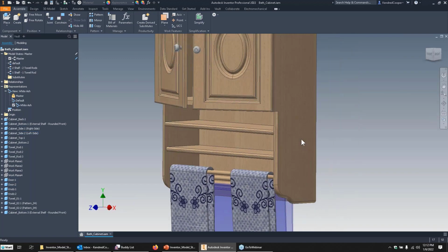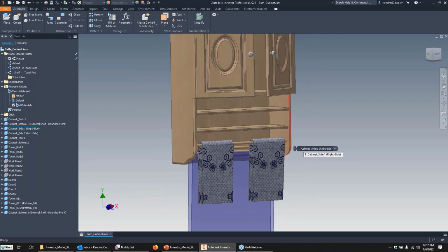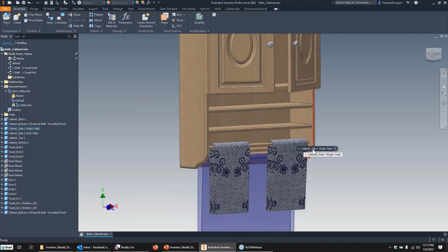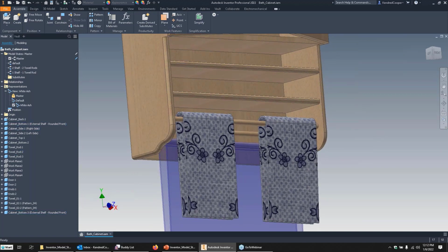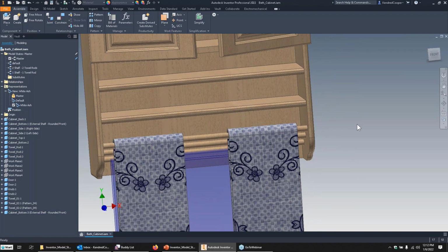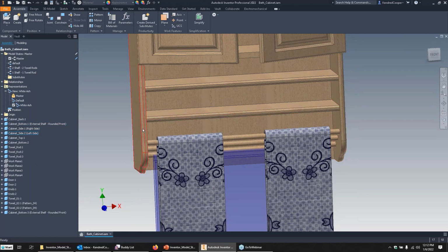Same thing for the side panels. That's really the big heavy hitter in this. I've got 3 different configurations. Well, 2, but I could have more. I've got 2 configurations already set up to where I can have 1 shelf or 2 shelves and either 2 towel rods or 1 towel rod. And working with those multiple configurations, the side panels have to change to, 1, accommodate for the dado cuts for the shelving, and 2, accommodate for the counterbores for the appropriate count of towel rods, whether it's 1 or 2. But they're the same piece. It's the same board.